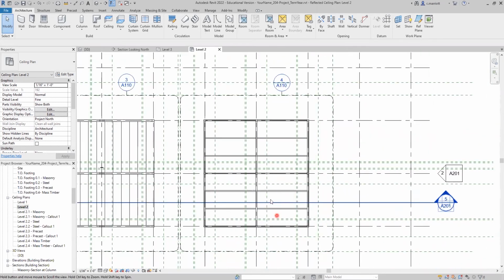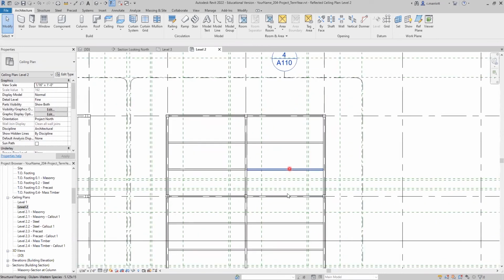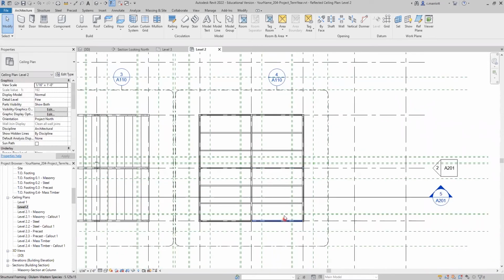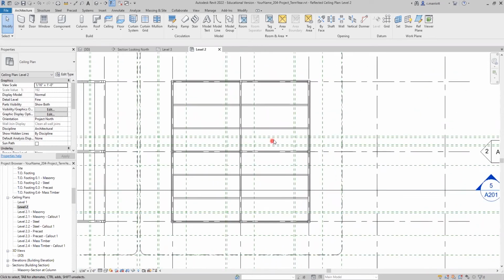So let's see here. These are 6.5 feet apart. I could put one drain, let's say, right here, maybe centered between the two. So that would be, since this is 25 feet across, 12.5 feet from the center line, and it would be 8 feet.